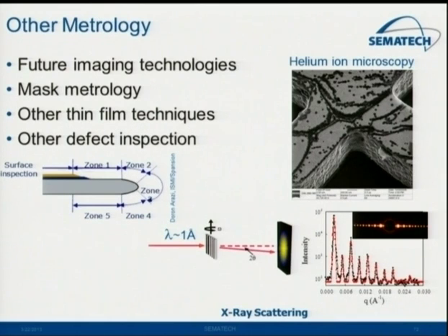On the optical scattering, again, maybe you go from optical wavelengths, visible wavelengths, to X-ray. So we have an active program effectively doing that scatterometry approach with X-rays. So you shoot your X-rays through your grating target, you measure the diffraction, and you can pull out information at even smaller dimensions. Hard thing is generating enough X-rays to make that practical today. So again, it's not used anywhere other than in some laboratory techniques.